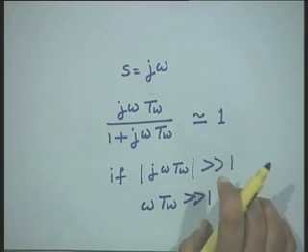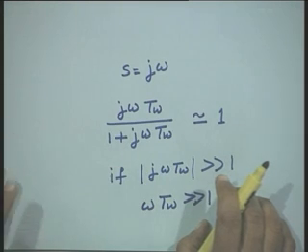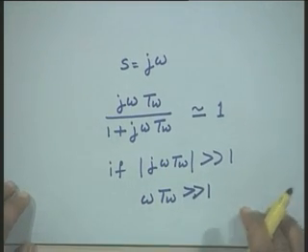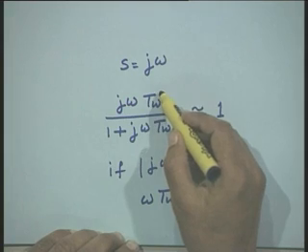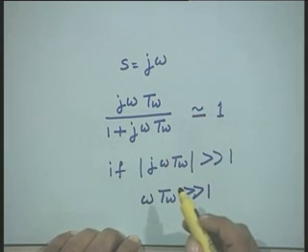Therefore, the speed deviation signal will be allowed to pass, and this washout block is also known as a high pass filter. Generally the characteristic of this washout block will depend upon the value of the time constant T W.